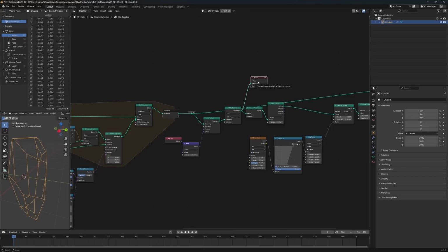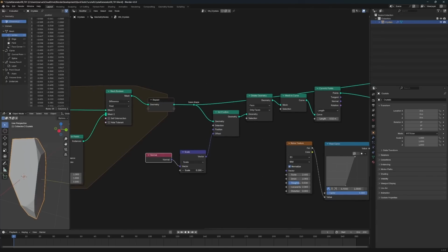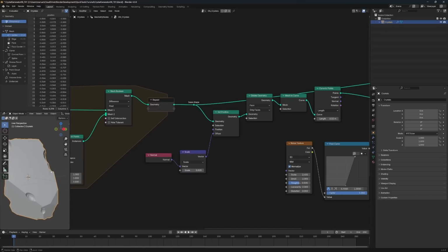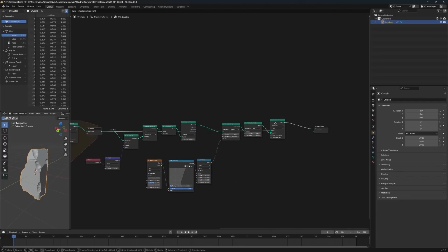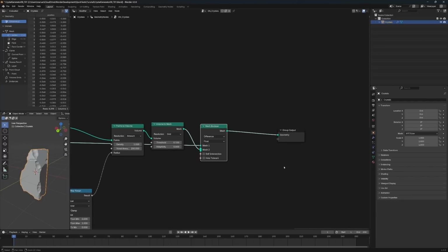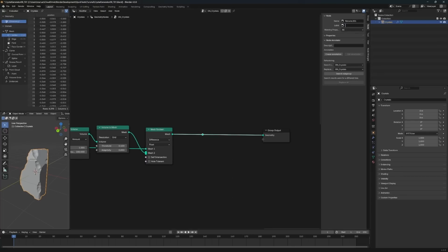And by getting rid of the viewer, we can see now we have a dial for specifying how deeply these objects are eating into the surface. 0.02 is probably a good value. And now the crystal looks a lot more organic than before. Before we continue, let's clean up again. This is noise stuff, and over here we have the second Boolean, and we can call this, by introducing another reroute, edge damage, like so.